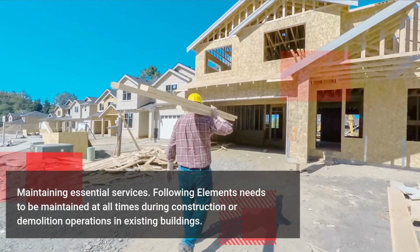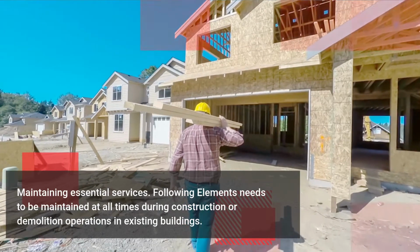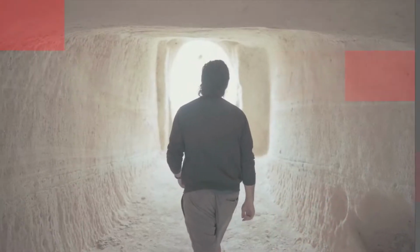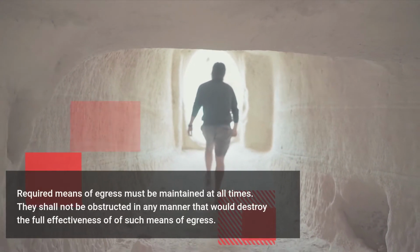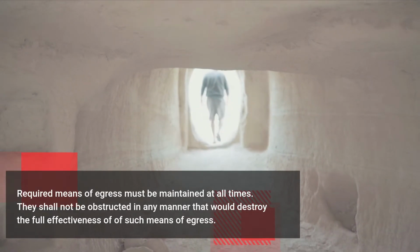Maintaining essential services. The following elements need to be maintained at all times during construction or demolition operations in existing buildings. Required means of egress must be maintained at all times. They shall not be obstructed in any manner that would destroy the full effectiveness of such means of egress.